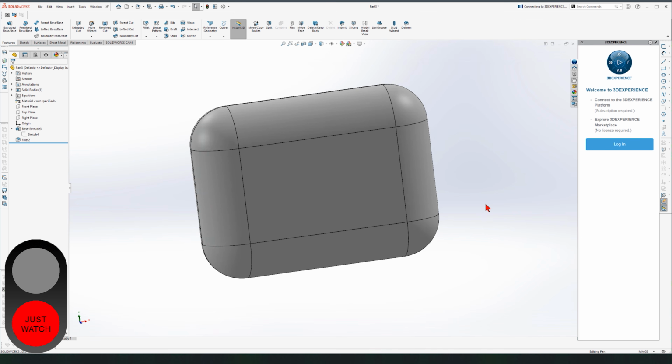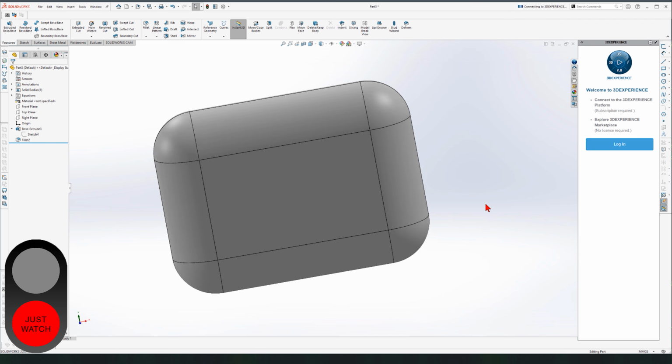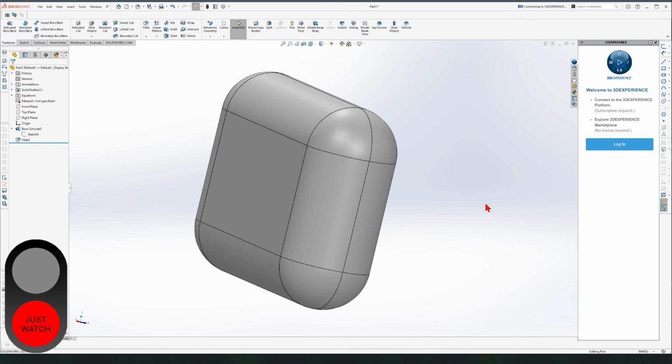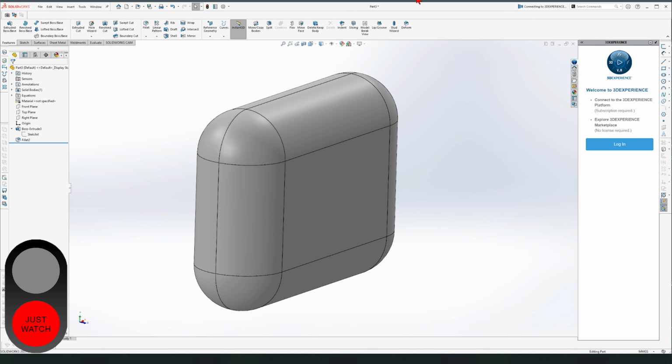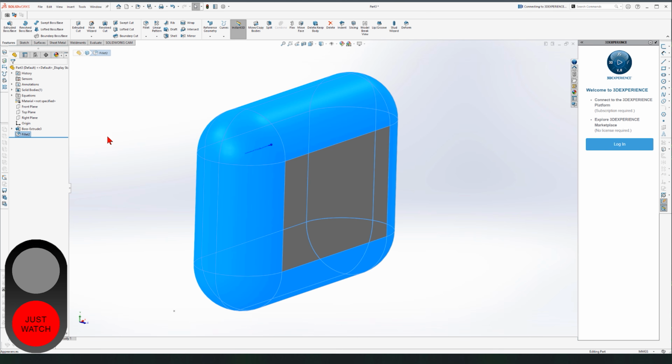Is this good? Okay. It's just a cuboid, and I have used the next feature, Fillet, which is inside the feature tab, and I have rounded the edges. It's another feature inside our design tree. Our design tree now hosts 2 features, the boss extrude and the fillet, right?